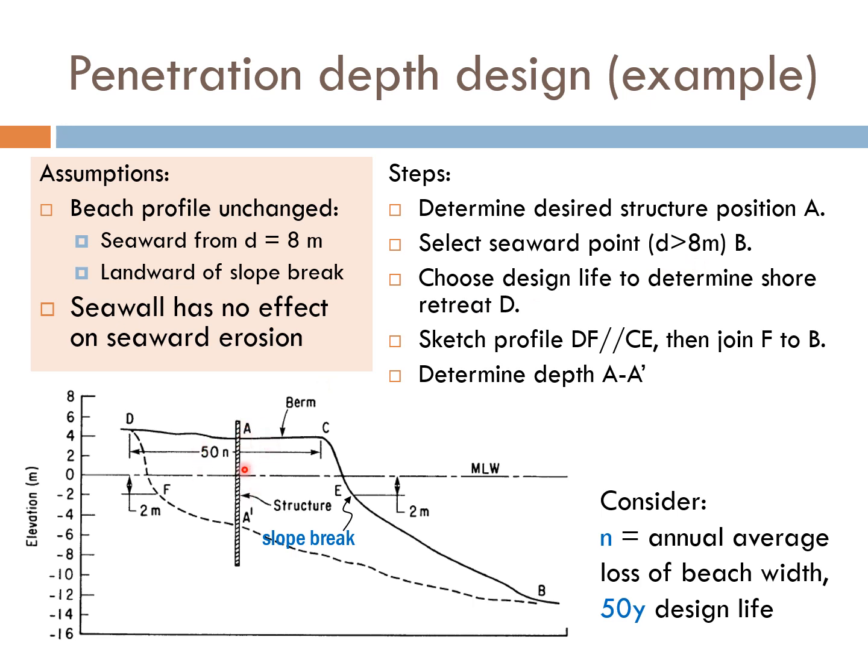So based on this location, we examine the seaward side and find a point B which preferably reflects the closure point of the beach profile, meaning that beyond this point we don't expect any profile changes due to erosion.